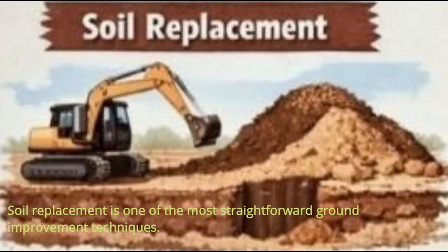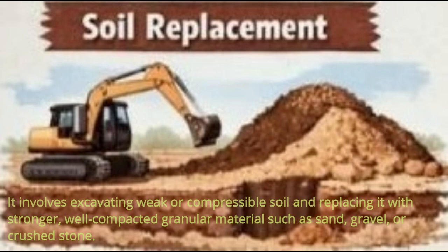Soil replacement is one of the most straightforward ground improvement techniques. It involves excavating weak or compressible soil and replacing it with stronger, well-compacted granular materials such as sand, gravel, or crushed stone.